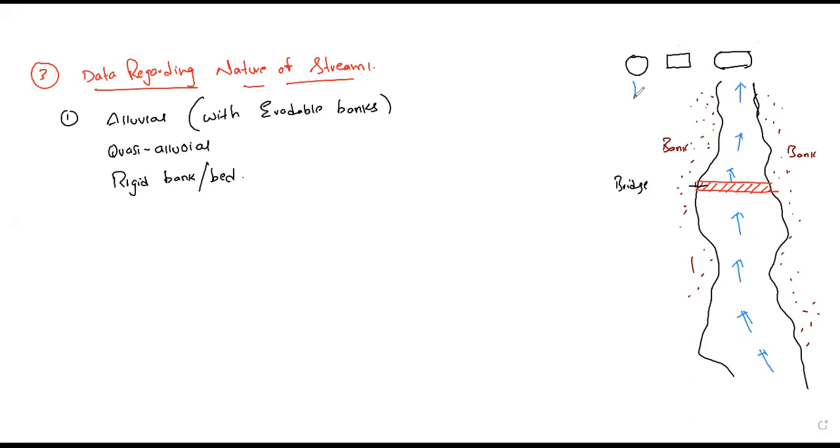If the water is flowing around piers, it can flow easily. If I make rectangular or square piers, and the water is flowing like this, these edges will get eroded. Understand? So based on the water flow, based on the velocity of water, the pier shape and pier dimension will be designed. A pier is a vertical member, a vertical column, right? That is very, very important.